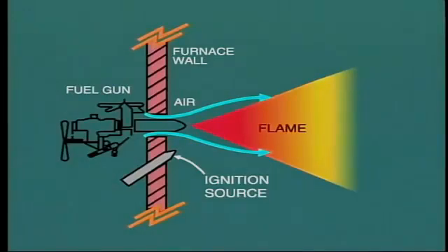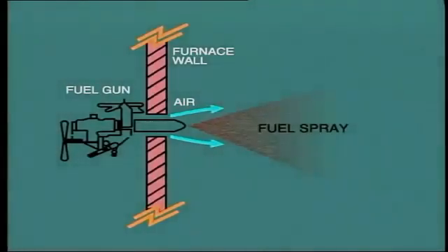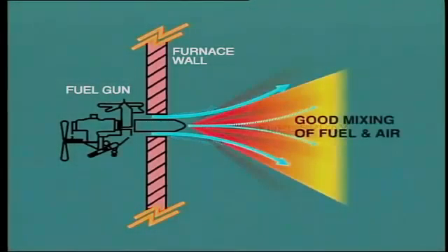Once the fuel and air mixture start to combust, the ignition becomes self-sustaining and no further help is required. The second item, turbulence, is extremely important. It is vital that the air comes into intimate contact with each tiny element of the fuel. In order to ensure this thorough mixing, some form of turbulence is created as the fuel and air enter the boiler through the burner equipment.